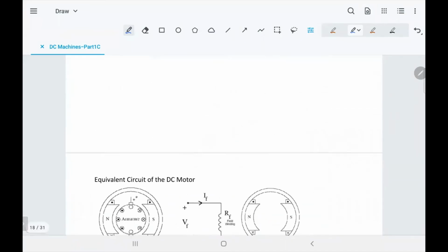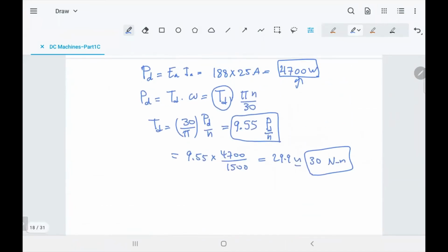Do you always solve for power developed first, like if we're asked for both of those in the same problem again, would we solve for power first to find the torque, or would we solve for torque and then solve for power? No, solve for power and then get the torque. Because the torque is as a motor. When you work as a generator, it will be the opposite way. You have the torque, then the power, because we have a prime mover. But now the motor is producing the torque. So first it comes from the power.